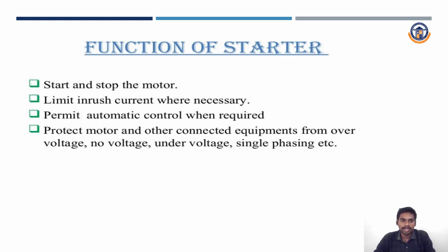Then the function of the starter is to start and stop the motor and limit inrush current where necessary. Because when the motor starts, the starting current is very high. So to limit the starting current, it helps the starter. It permits automatic control when required, and protects the motor and other connected equipment from over voltage, no voltage, under voltage, and single phasing, etc.